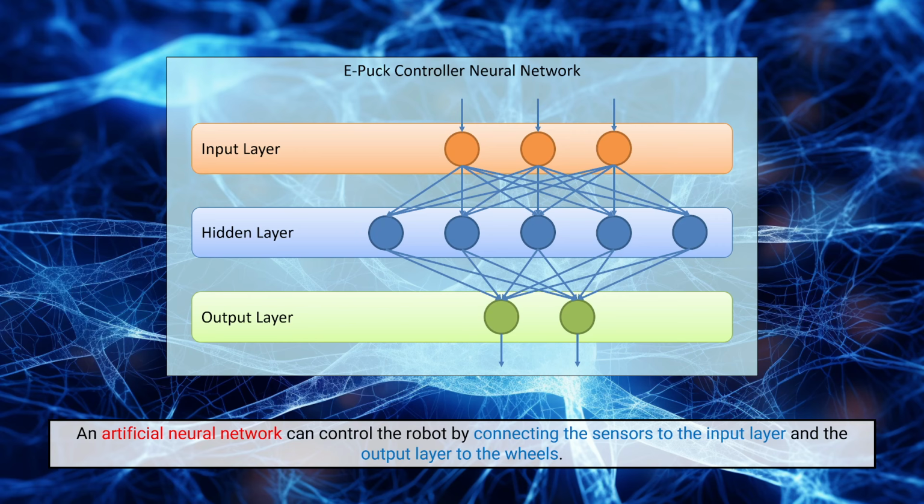And that measurement is going to come into the input neuron and then be passed out to all of these hidden neurons as is. So we usually normalize the infrared sensor in some way so that if it wasn't originally coming between 0 and 1, we normalize it so that it's between 0 and 1, and then we push that into the neuron and use that as our signal moving out.